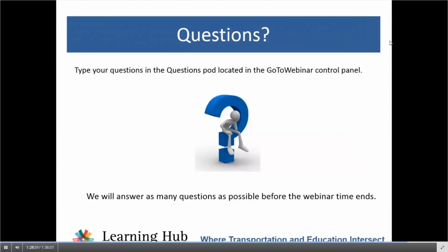So no, that I know of, there's no specific method in development to look at two-way center turn lanes. I think they would be treated as two de facto left turn pockets. So you would take the two-way center left turn lane and divide it into approximate turn pocket lengths, and then evaluate them that way.